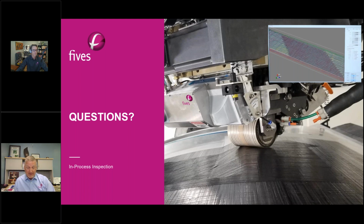And that's one of the biggest limitations of the LLT systems, which we employ. We use those today on simpler machines, ATL machines, on mild contour, because once you get above, I'll call it 10, 15 degrees, there's not enough data and you get a lot of false positives. But yeah, complicated parts, that's one of the reasons we went with this sensor.